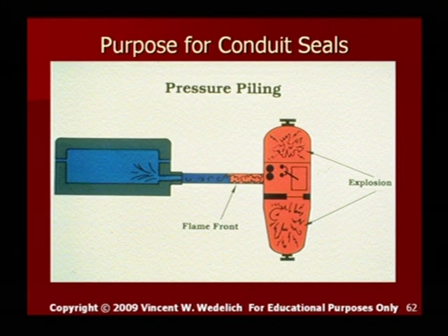And what they found out was the installing contractor had run a conduit and found another conduit that was a 4-inch conduit, tapped into it, and kept running his wires. Well, what he did was he actually tapped into an explosive environment. And by doing that, he allowed gases to flow up in this line, and then when this electrician was opening and closing the circuit breaker, he was actually providing the ignition source. So he's lucky he didn't get hurt, and the installing contractor had to go back through there and install a seal. That's what you do, is you install a conduit seal to stop this.